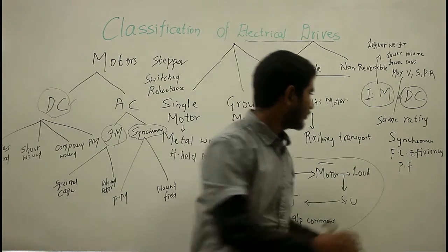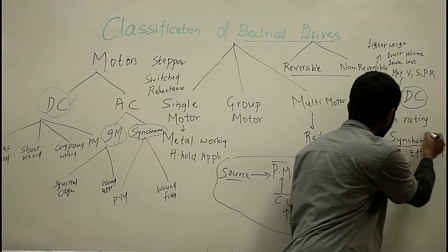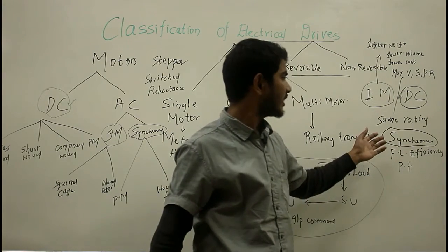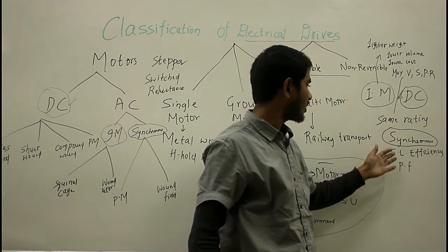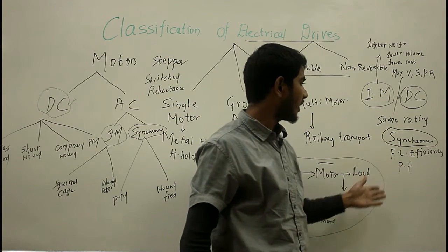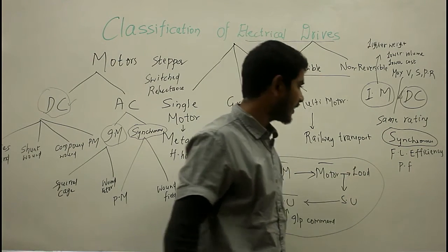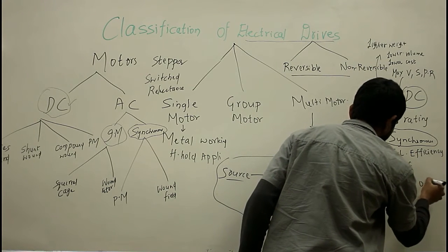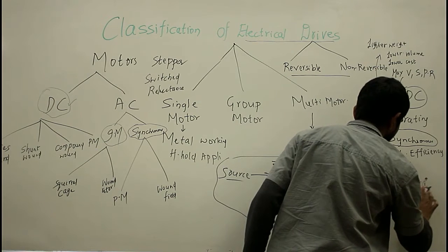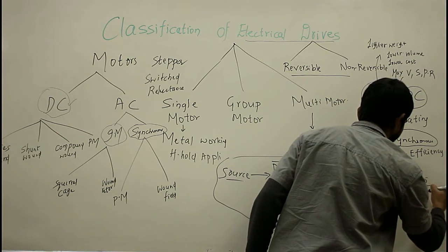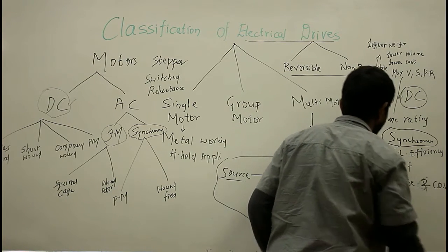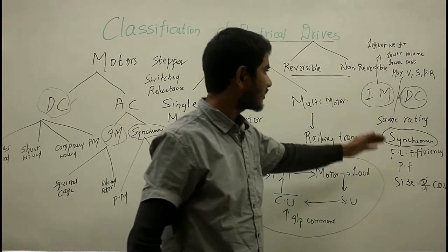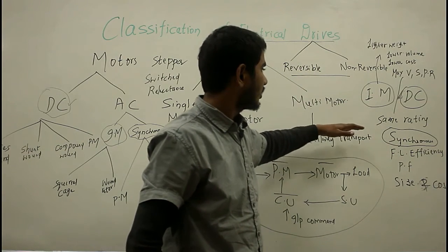If we consider a synchronous motor of the same rating as an induction motor, the advantages of the synchronous motor over the induction motor are the full load efficiency and the power factor, but on the other side the size and cost of the synchronous machine are higher than the induction motor.